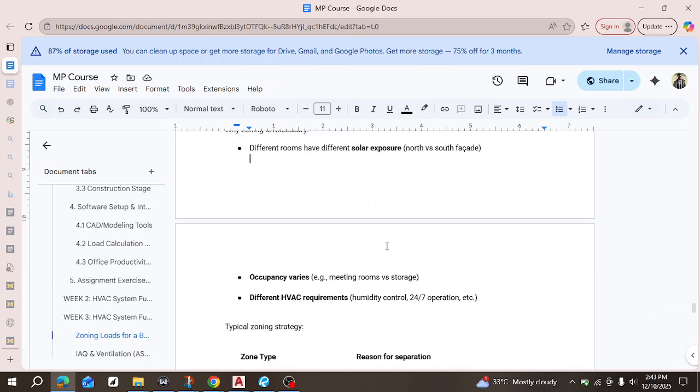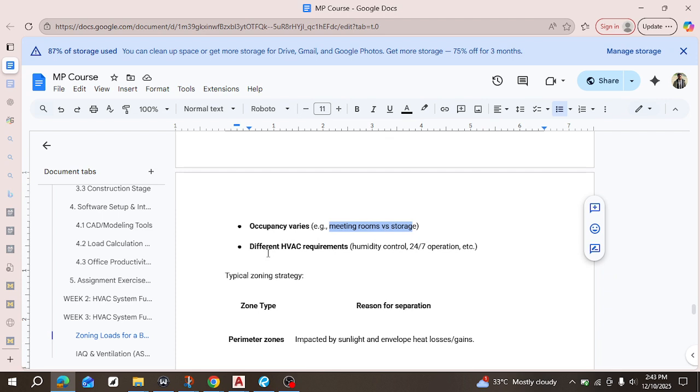Another factor we talk about is occupancy, which depends on the content of that space. If there are a lot of people, it means that place needs higher cooling or higher heating or higher air change. Then we also have storage. There are some spaces that are storing either food items, or maybe it's a computer room or a data room, that need to be kept at very low temperatures because it helps to preserve these things. And then humidity needs to be controlled too.